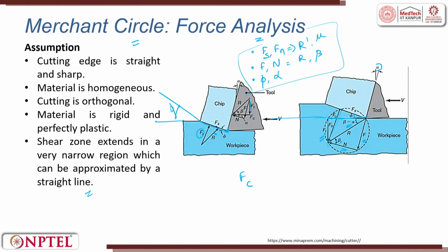Fc is the cutting force because of the resistance given by the tool on the chip. That direction is Fc, the cutting force, and perpendicular to the cutting force is Ft. Now, we have found out the cutting force and the tangential force.